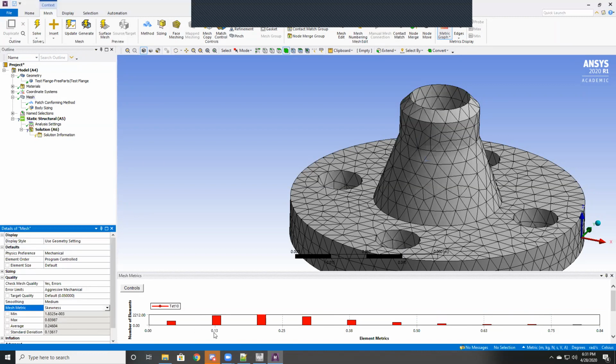It's moved the averages over a lot, which is good, but just note that there's a kind of a limit to how much of an effect you're going to get, and it's usually these worst cells that are going to mess up your solution the most. We're going to stick with this because it'll give us a good balance of runtime and detail.